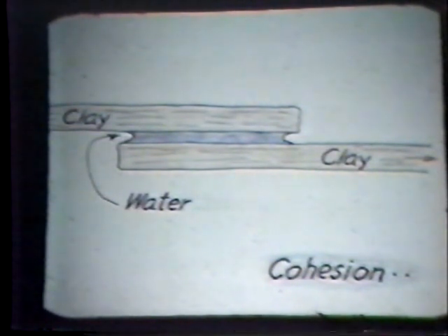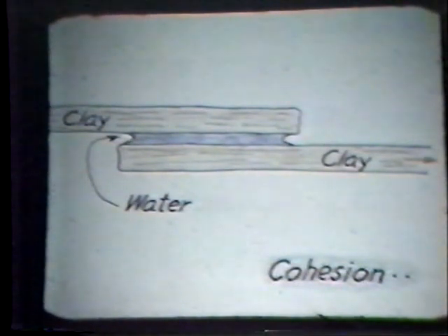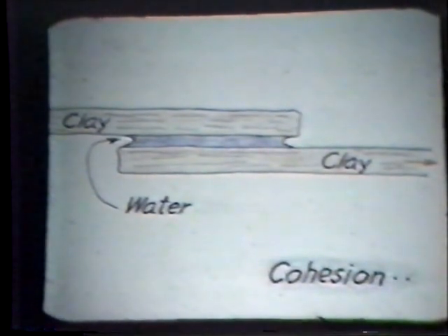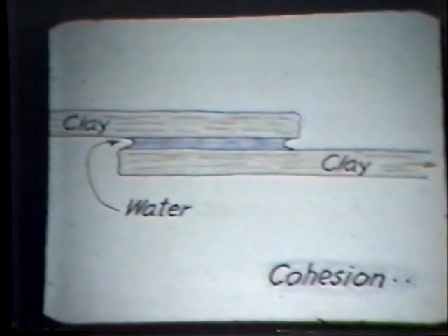specifications for gravels to go into roads usually recommend that if you're going to put some kind of an impervious surface over the top, a seal coat, asphalt, whatever it might be, you want to have less than 10% of the material passing the number 200 sieve. Less than 10% finer than 74 microns. Less than 10% in the silt and clay size particle range.